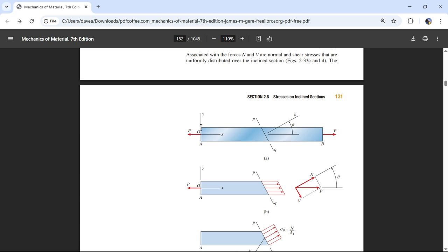And so you definitely still have that aspect where if I had tape right here and here, and put these two pieces of wood together, and I put a force this direction and a force this direction, hey, there's very little tape that's holding those two forces in shear, so maybe I could shear it quite easily. And if you're just using tape, yeah, tape isn't very strong in tension, so if you actually just put double-sided tape to hold two pieces of wood together and pulled on them, they're not going to be very strong.